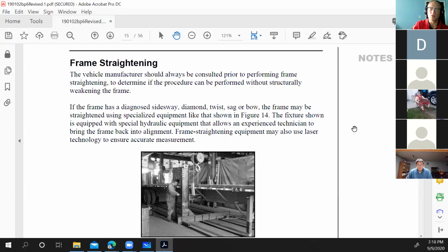When those got seized in, you would just take an air arc and you could just sink it right through the center of the kingpin, and that would loosen it up really easily. But you had to be careful not to hit the bore on the axle, the bore for the kingpin, because yet again, if you weren't going straight down, any metal that touches it turns to liquid.